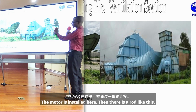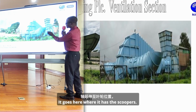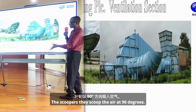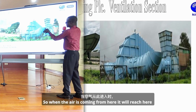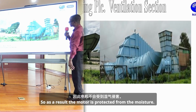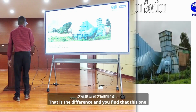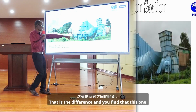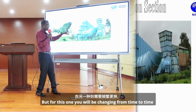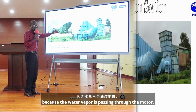The motor is installed here. Then there is a rod like this. It goes here where it has the scoopers. The scoopers scoop the air at 90 degrees. So when the air is coming from here, it will reach here, then it will be scooped up to the atmosphere. So as a result, the motor is protected from the moisture. That is the difference. And you find that this one may last close to 50 years without problems. But for this one, you will be changing from time to time because water vapor is passing through the motor.